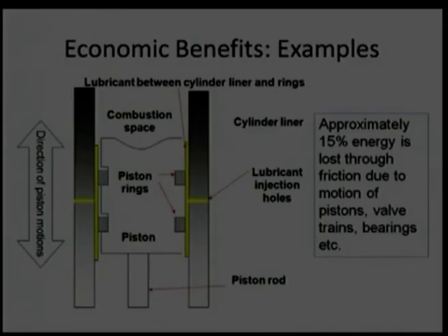If I try to utilize good tribological knowledge on those IC engine components, there is a possibility of reduction in friction by 15%. 15% has generally been targeted. People have quoted that they have achieved around 20% saving in friction. Their mechanical efficiency has reached 95%, and in older times the mechanical efficiency was maybe 60%, then 70%, and maybe around 3-4 years back it was 85%. Now people have achieved 95%. So, great saving due to tribological knowledge is possible.